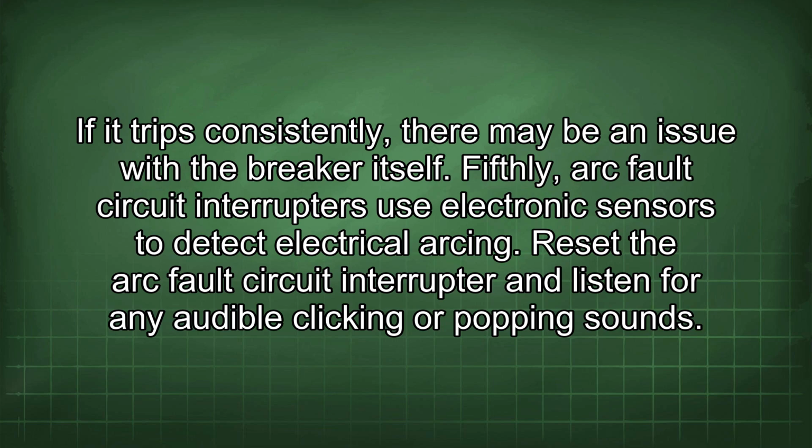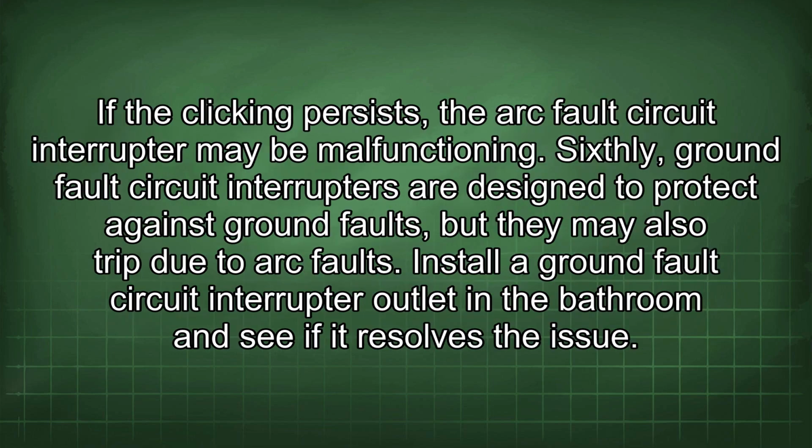Fifthly, arc fault circuit interrupters use electronic sensors to detect electrical arcing. Reset the arc fault circuit interrupter and listen for any audible clicking or popping sounds. If the clicking persists, the arc fault circuit interrupter may be malfunctioning.